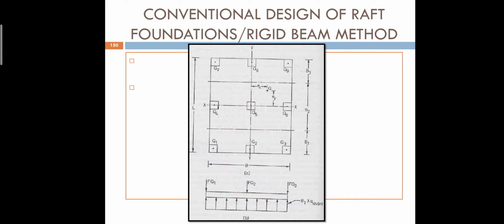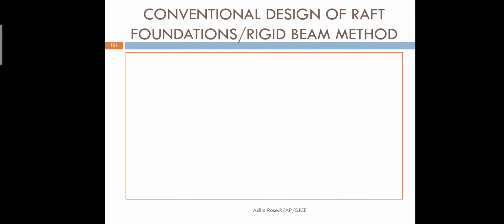Similarly, the effect of the load in the third strip will be there on the second strip. They are not independent, they are all actually connected. So logically the effect of the other loads will be there in each strip. ஒரு ஸ்ட்ரிப்புக்கு இன்னொரு ஸ்ட்ரிப்புக்கு மேலே இன்ஃப்ளூயன்ஸ் வில் பி தேர். ஸோ they are not actually independent.